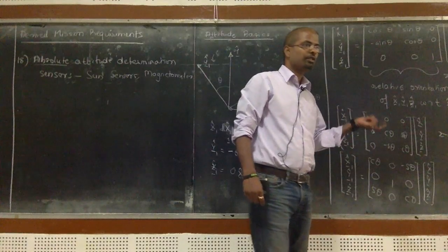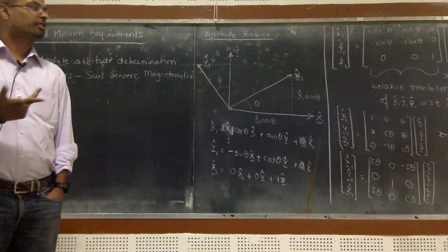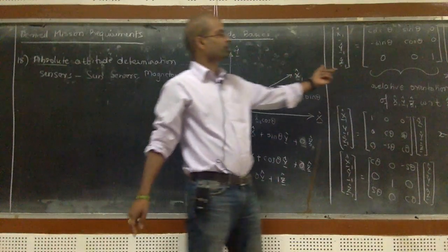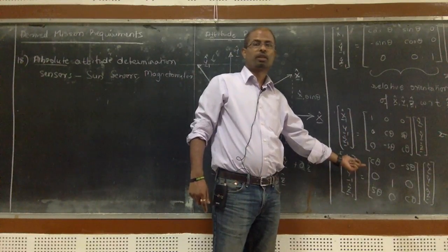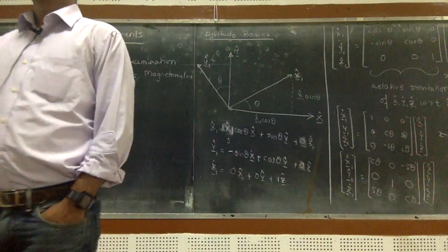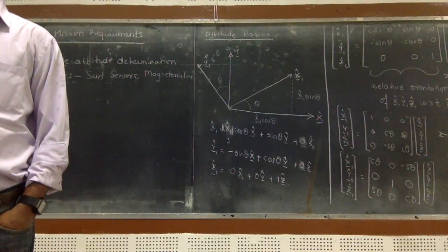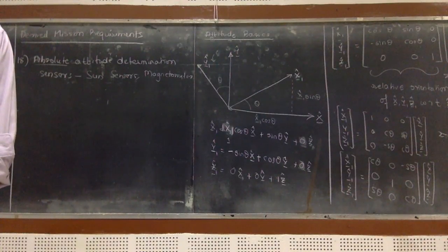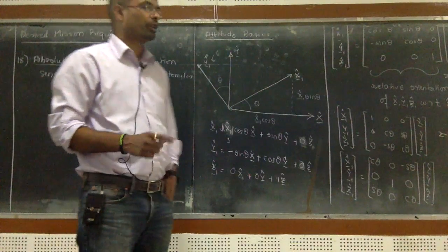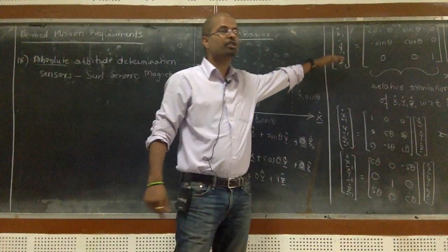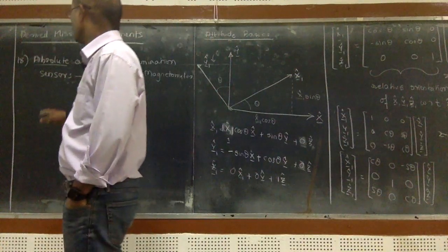You understand? So these are called fundamental rotations. Fundamental rotations are rotations about the fundamental axes. How many axes are there? 3 axes, right? So this fundamental rotation is about the z-axis, this one is about the x-axis, and this one is about the y-axis. Okay. Any complete rotation, think about this. If you are expressing position, how do you express it? You say this is this much x, y, and z, right? So similarly, when you do the complete orientation, you can express it as a combination of x-axis, y-axis, and z-axis. A complete rotation, and that is required.